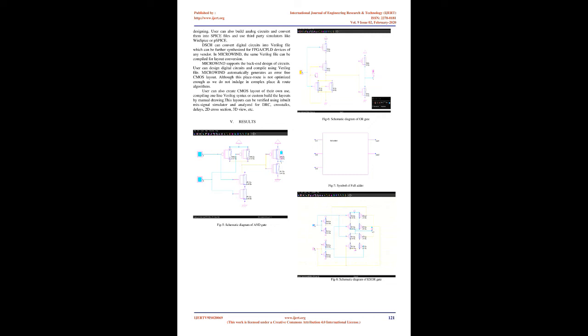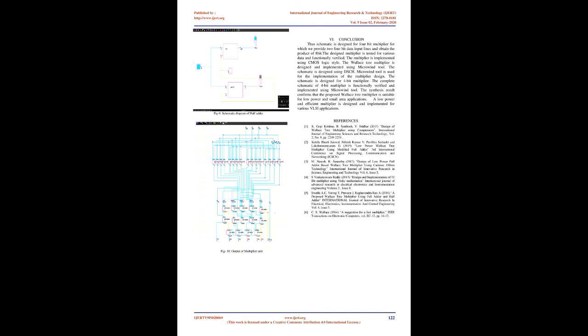Carry look-ahead adder. Function: the carry look-ahead adder, CLA, adds 2 numbers with very low latency. Algorithm: by extending C with the corresponding inputs, the carry and sum are independent of the previous bits. Wallace multiplication. Function: the Wallace tree module adds the 4 partial products and generates 2 intermediate operands for final addition.